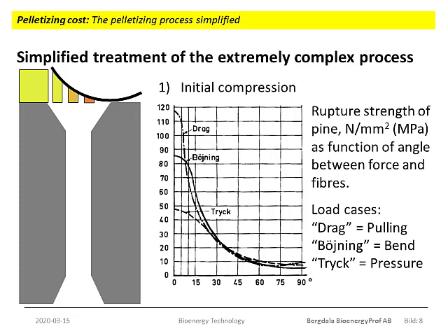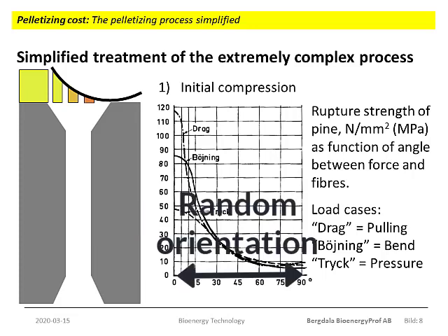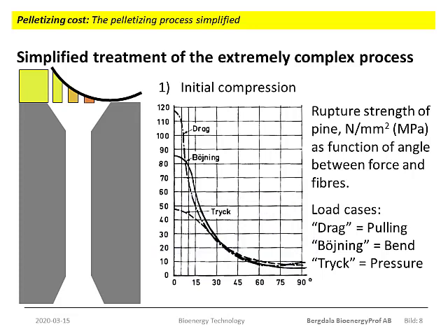So what can be said from this is that if we want to crush the cell structure, we will have to apply a pressure exceeding 50 megapascal. The fibrous particles will be oriented at random. So now go back to the paper by Henriksen and co-authors and scan section 5, which is concerned with the structure of wood. As you will see there, the particles may well have a pronounced fibrous structure. And with the random orientation, some particles will be crushed at 50 megapascals, while others may just be slightly bent. But we can be pretty sure to destroy a major part of the cell structure.